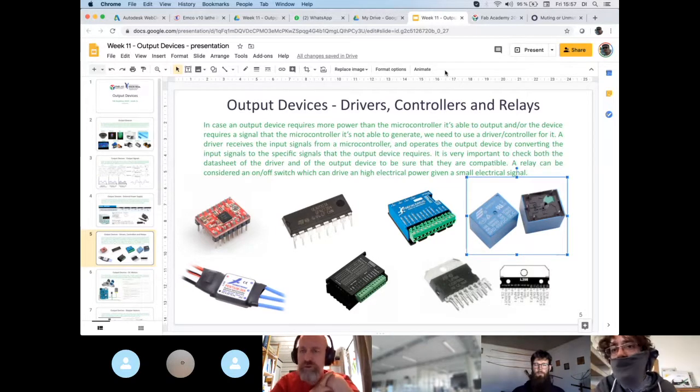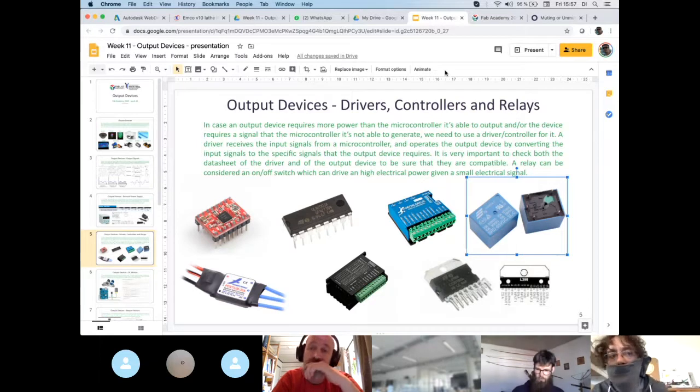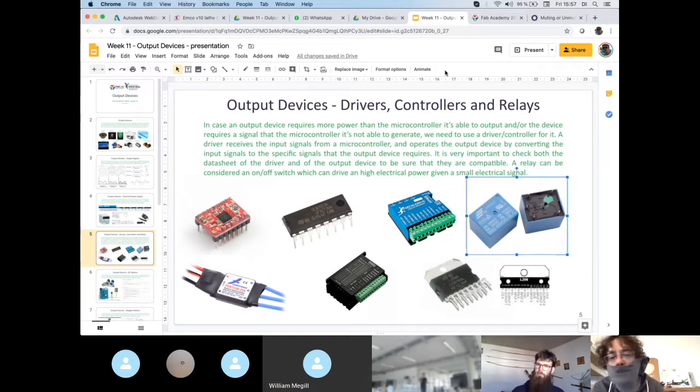That's what I wondered. Okay. Yes, that's it. And the advantage is that some of these solid-state relays have the name of solid-state relays, but they are giant MOSFETs, so you can control all the states in between, even from on and off. Some of these solid-state relays, you can just use them as giant MOSFETs. So you can say 50% of the power, 60% of the power, and so on. So there is another advantage, of course.